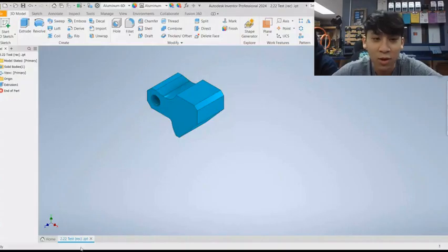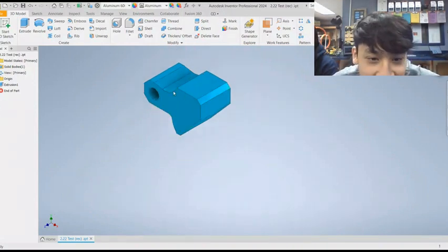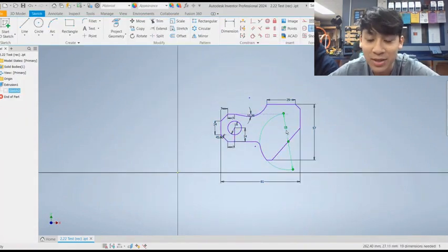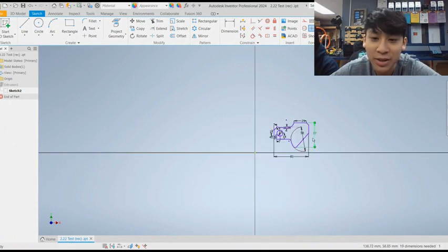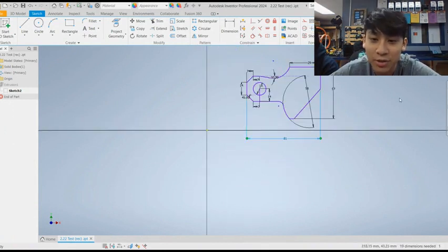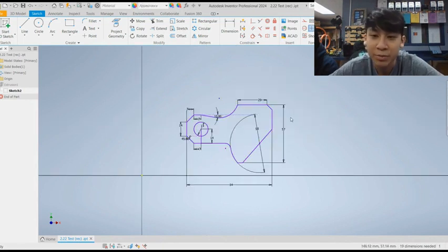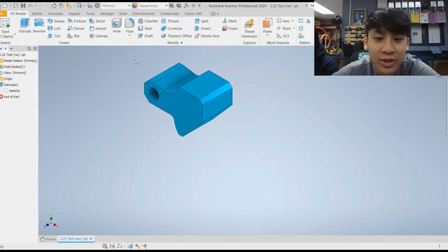Alrighty, question 2, let's get started. You want to open up your first sketch, and this is going to be your A, this is going to be your B measurement. You want to change this to 84 and change your B to 59. Finish sketch, and it should adjust.